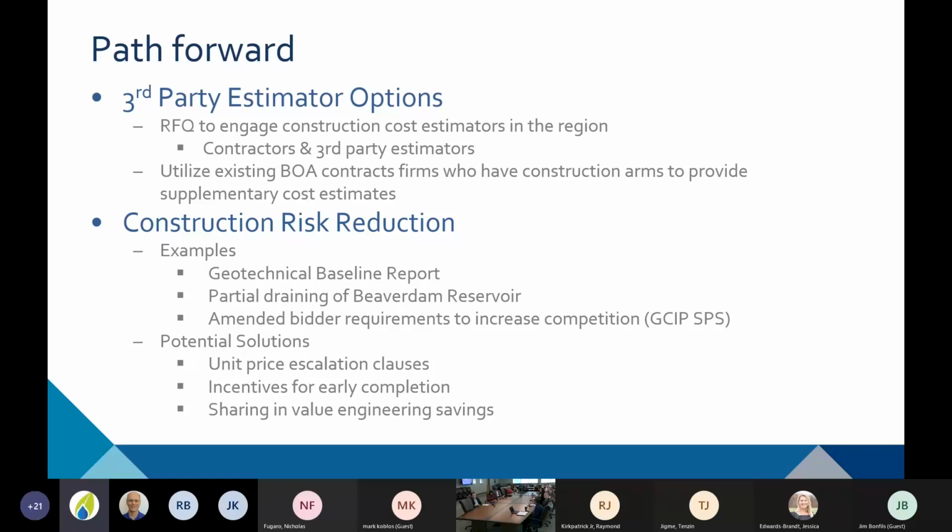So it creates a kind of level playing field and everybody understands what the geotechnical engineer has assumed the subsurface conditions will be. And then that also gives us an opportunity, if we come across some differing site conditions, a place to negotiate from, right? So we've established a baseline up front. And so with the bids, hopefully there'll be less risk on the contractors for assumptions that they have to make on the heavy civil part.